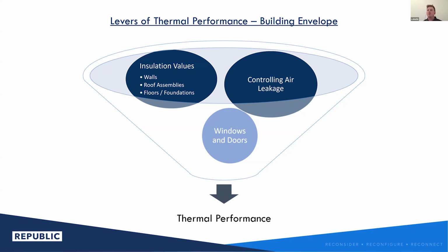I mean, windows and doors are something that definitely can't be forgotten, and making sure that they're installed in such a manner that they're airtight, they're resilient, and they will be durable throughout their projected lifespan. But again, coming back to air sealing, looking at windows and doors and managing these penetrations is really key to ensuring that the insulation that you're putting on your building is really providing its full value.